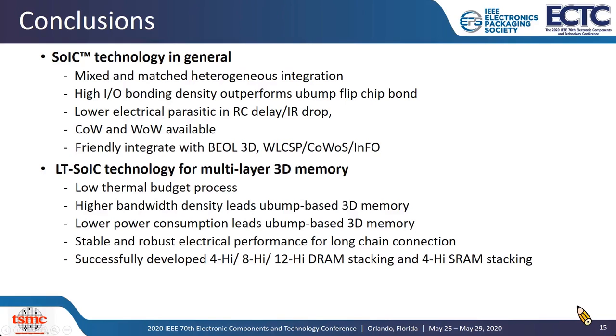Our newly developed low-temp SOIC technology for 3D memory provides a low thermal budget process. It can offer both higher bandwidth density and lower power consumption, which outperforms microbump-based 3D memory. Stable and robust electrical performance can be achieved for long interconnection chains. Most importantly, we have successfully developed 4-high, 8-high, and 12-high DRAM stacking, and also 4-high SRAM stacking.